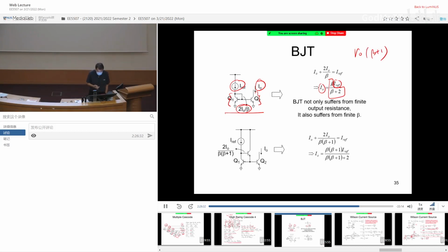One straightforward way to improve it is very similar to the so-called Darlington pair. So you include one more transistor over here. The good thing is that by doing that, you are actually making the current smaller, because unlike here, where the IREF right away branches out to the beta, here, although there is an IB, because of this additional transistor, it becomes IB divided by beta.